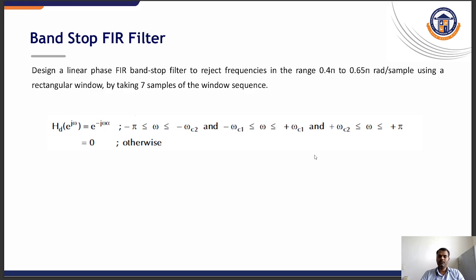So this is a fundamental difference that indicates that it is a preferred choice for applications where stability and phase response are important. The key property of the FIR filter is that it has a linear phase response. This means that all frequency components of a signal are delayed by the same amount of time. This uniform delay prevents phase distortion, which is important for preserving the integrity of the signal's waveform. For example, in audio processing, a linear phase ensures that all frequencies arrive at the output at the correct time, maintaining the natural sound of the audio.